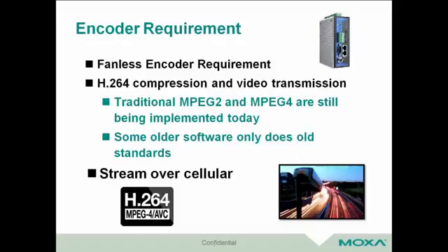Lastly, in regards to this, the traditional codec is MPEG-2. They're all migrating to MPEG-4 as well as H.264. Usually now a lot of IT designers would go with H.264 only because it's a better compression and you can move that data in a shorter bandwidth.